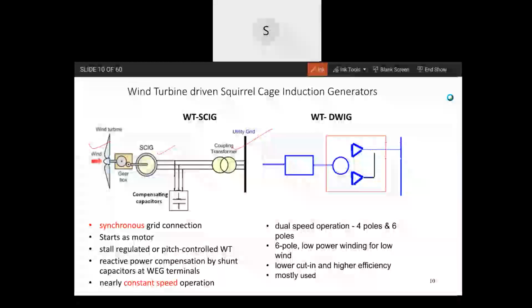But that acceleration time is significant. During the acceleration time, that's a few seconds, sometimes more than a minute, there will be loss of generation, meaning loss of energy. Wind may be there, but still you are not able to extract it because the machine has to come into generating mode. With a 4-pole machine, initially it was working, then the wind fell, wind speed came down.